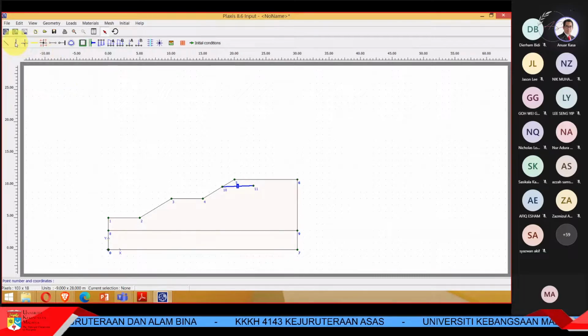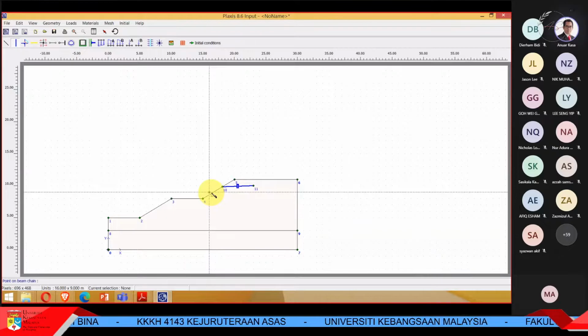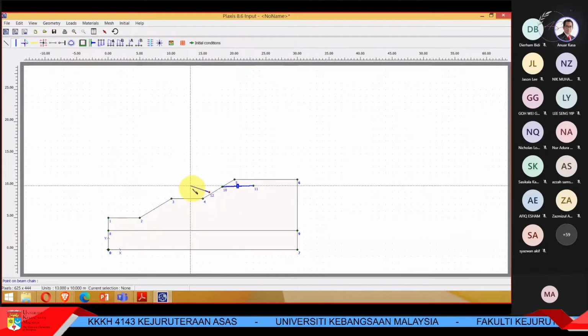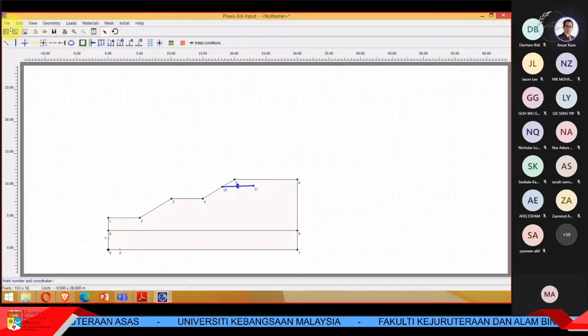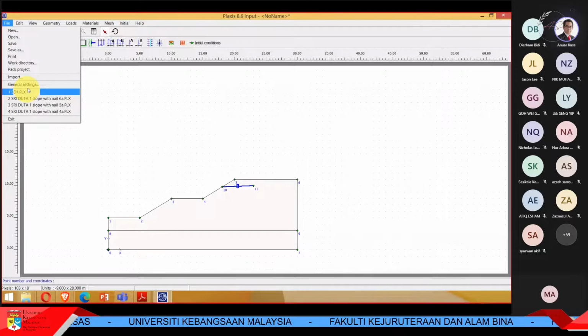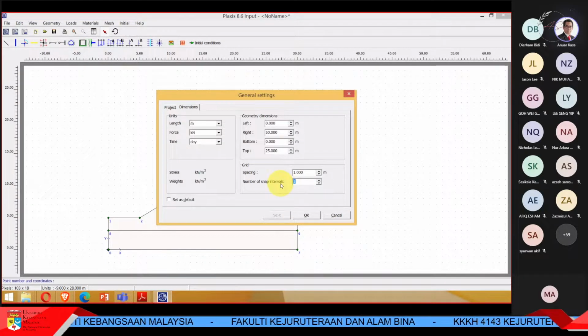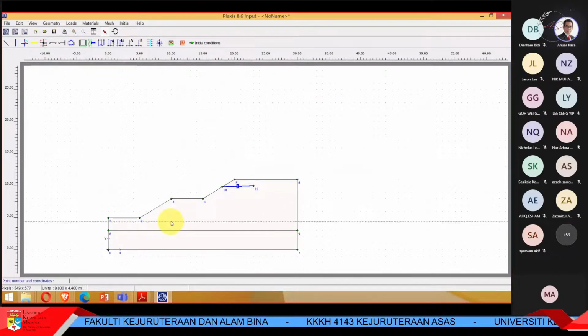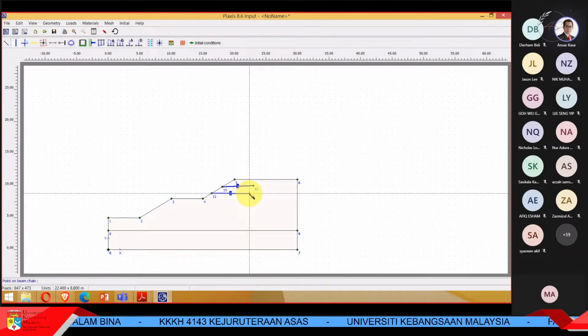Okay, the thing is, I use the snap function. So it is snap to other point. I can also make it for the snap here, maybe I make it 5. So every 0.2 meter, so it is more dense. Let's say I want to have 2 reinforcements here. Okay, something like this one.